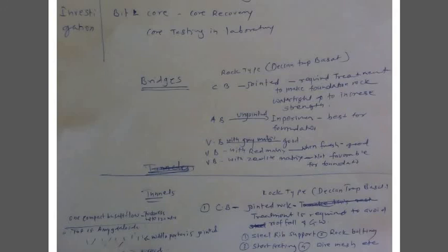So this is about the time of taking foundation. As far as the dam is concerned, you can take the foundation of the dam on the top of the compact basalt, because there you are taking the foundation on amygdaloidal basalt, which is impervious. But if you take the foundation at the central or middle part of the compact basalt, joints are there, and if the frequency of joints is high, and they are interconnected with each other and are consistent joints, then leakage of water will take place.